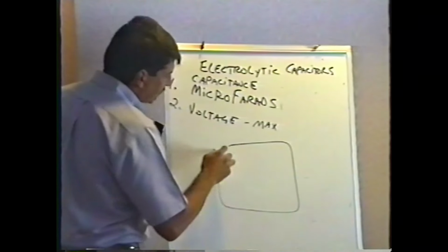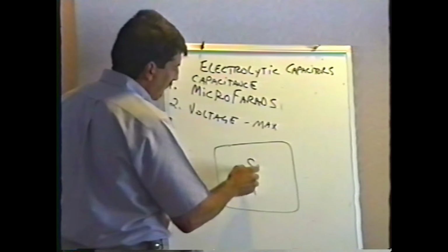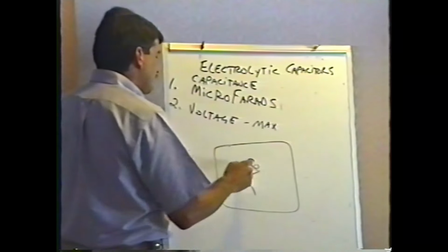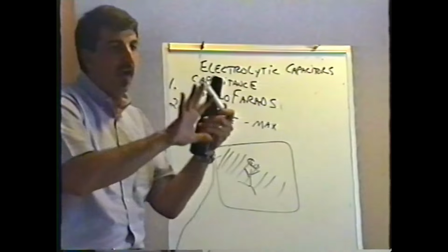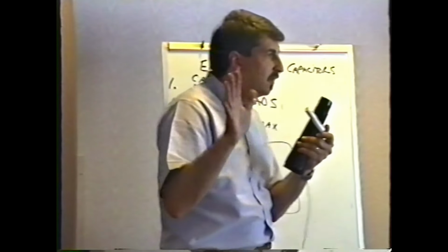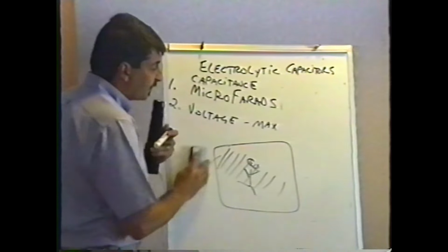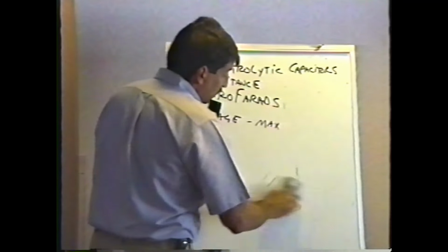Sometimes you've seen this on the screen where you see the video game playing, whatever the game is, and you see these diagonal lines, very closely spaced, kind of drifting all around the screen. It's called herringbone interference. That comes from the bad capacitors in the power supply. We'll talk more about that on Wednesday.